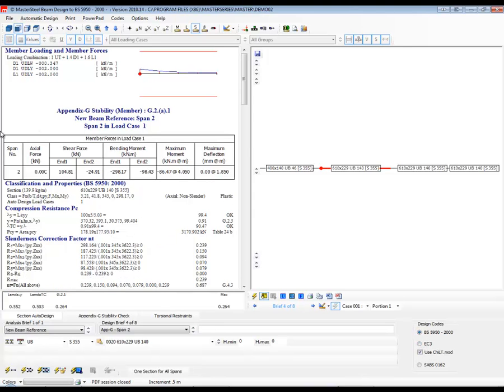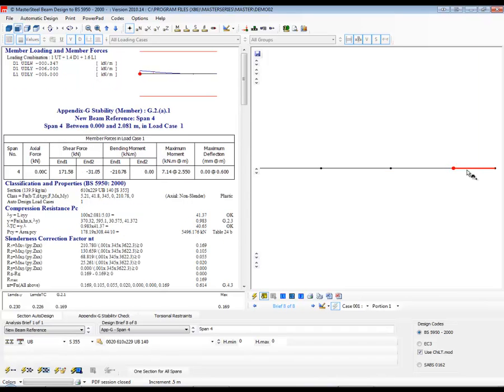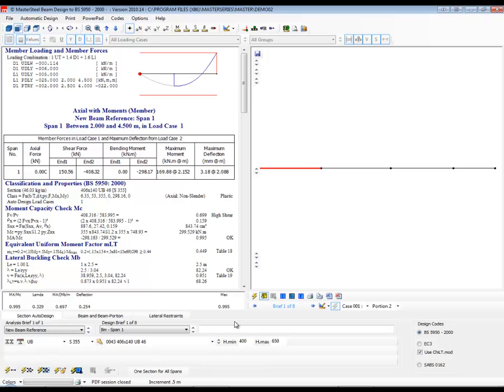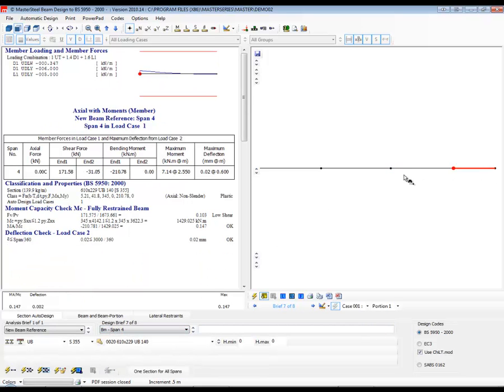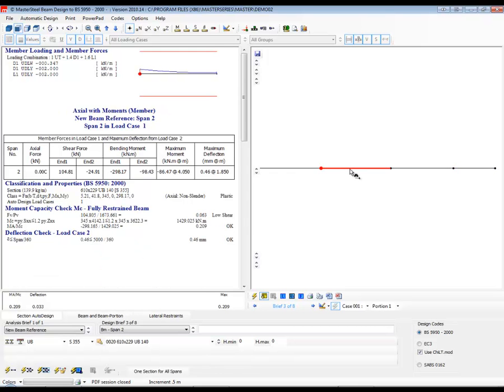If you went back to a more familiar BS, just for simplicity of design, then you would see it being more applicable. I'm just going to turn off my section sizes and put on little dots so I can see my beams a lot easier. And we can see that the sections that we use can be chosen, the design can be chosen by picking the member. We don't have to drop this list.